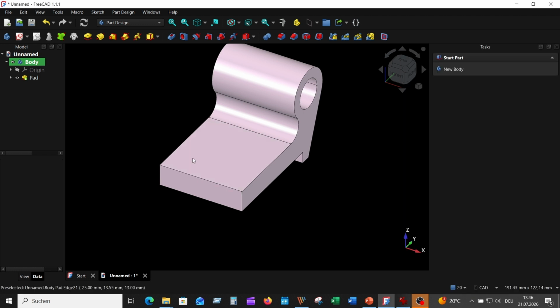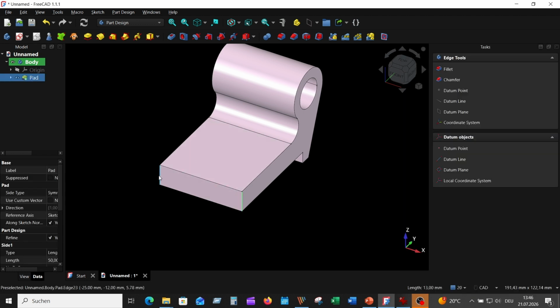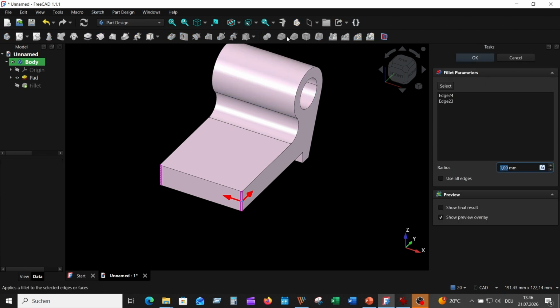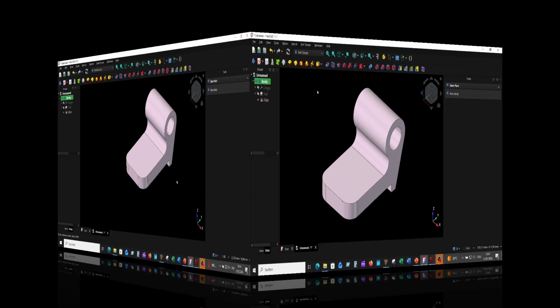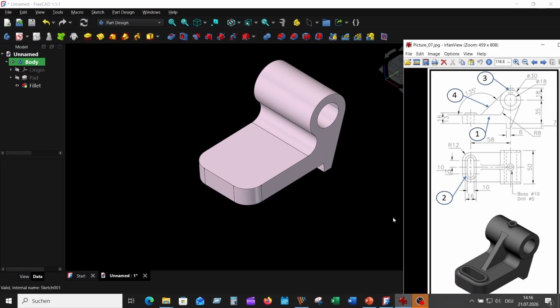Now, we add a fillet with a radius of 12 millimeters to the edges. In step 2, we sketch the slot profile on top face and then we create the hole with the flange. Select the top face and then activate the Sketch tool.